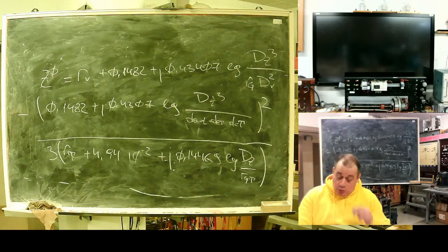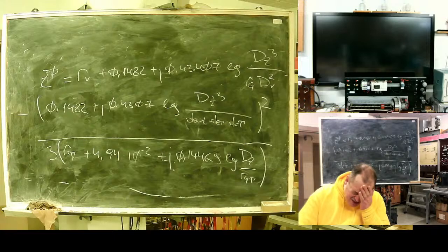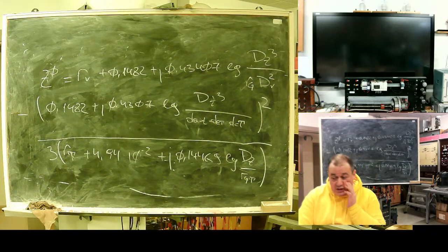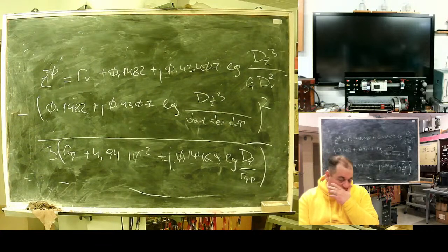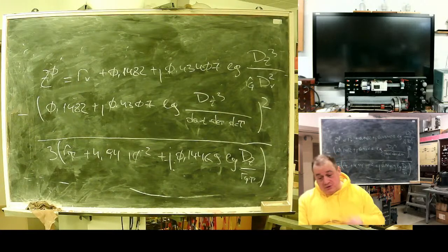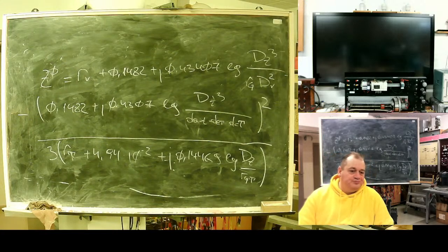That's what you need to put in your model. And it's only a low frequency formula and with a small shortcut, assuming the line is fully transposed. For a non-transposed line, you will need to do a step back and your formulas will be bigger.